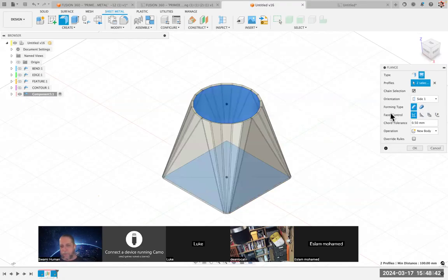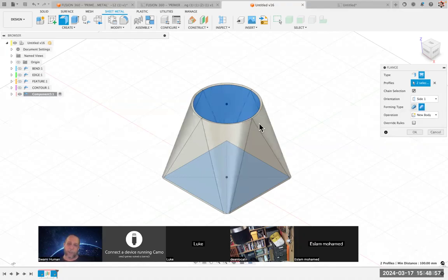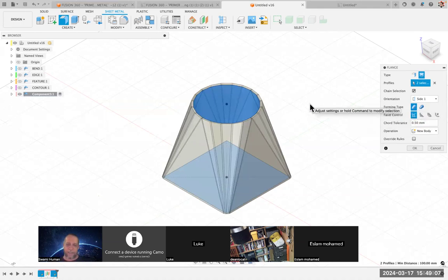And take a look. So right here, we have the side that it goes from, the forming type. The first one default is a break form. This one is a die. If we click die, it's going to be smooth arcs, so that material has to get bent in one nice smooth piece. The default, which we're going to use here, is a break form, and it's faceted in some fashion. That would be doable in a solid model, but there'll be a lot more work. So we are going to keep that one.